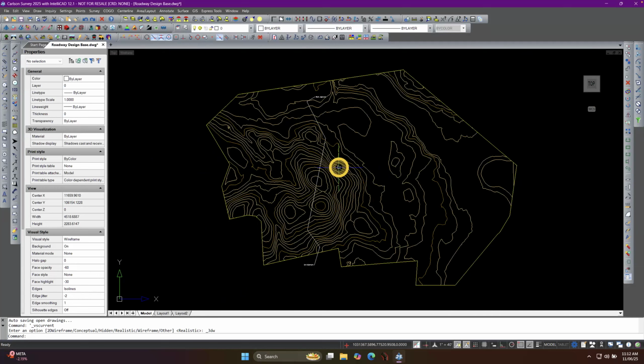So now, how do we get that surface information available to us? Any thoughts, any ideas? What would we normally do if we were given this as a drawing, let's say they were just drawn polylines, they weren't this special object? What we typically do would be create a surface, call it existing ground, for instance, and wherever we get the data that defines that existing ground, in this case, all we have are contours, right?